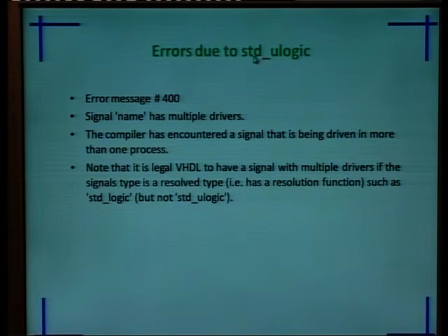If we have std_ulogic, there may be an error message like this, which shows at which line the error is, and then the signal name that has multiple drivers, meaning multiple inputs are there, but which input will be considered at which time is not specified, meaning which input has higher priority and which has lesser priority, that we have to specify, or we have to define the resolved logic.